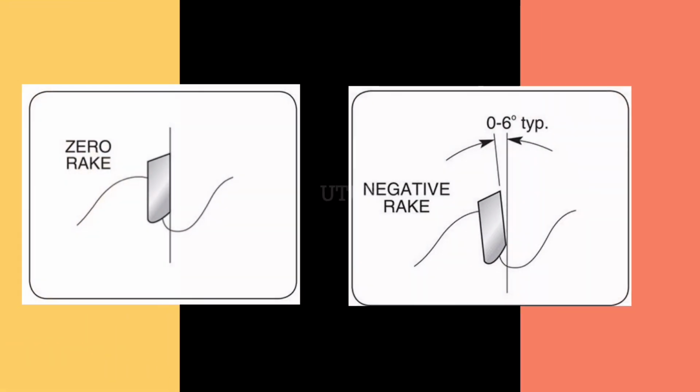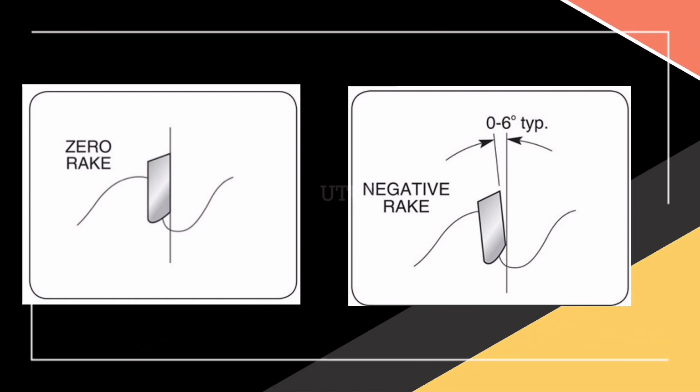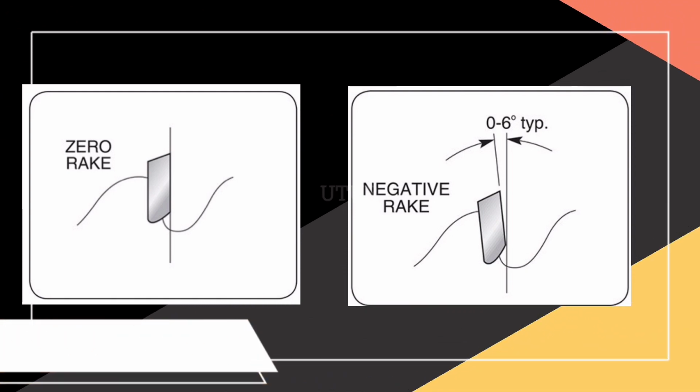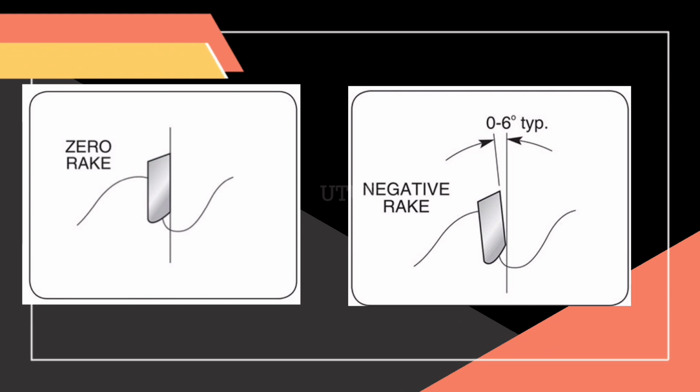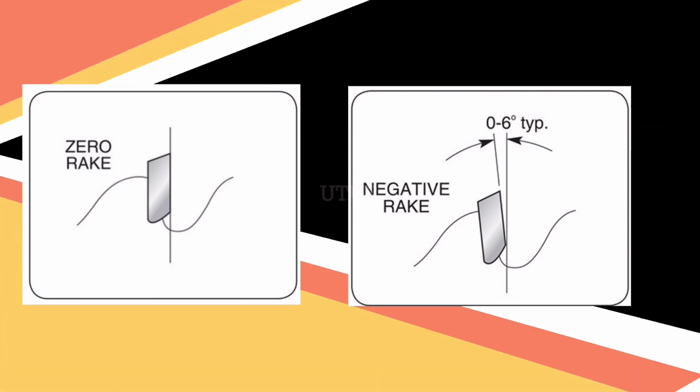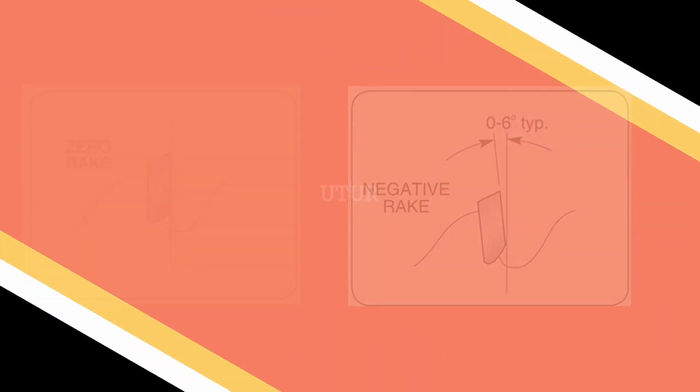Blades which have a zero rake or even still a negative rake are best suited for use on a radial arm saw, table saw, and miter saw because they prevent climb cutting and self-feeding. Sometimes you will find the hook angle caveats labeled on your blades. In conclusion, your hook angle determines how steeply your tooth leans into the cut.